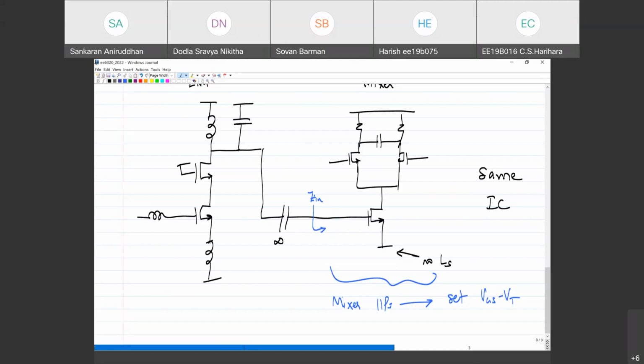Yes. So what kind of impedance is that? I mean, purely resistive impedance. No, it's not. Please think about it. Zin will be omega t times R by omega. That is not purely resistive. That is frequency dependent. By omega, sir, that is a capacitor. Yeah, it will look like a capacitance.